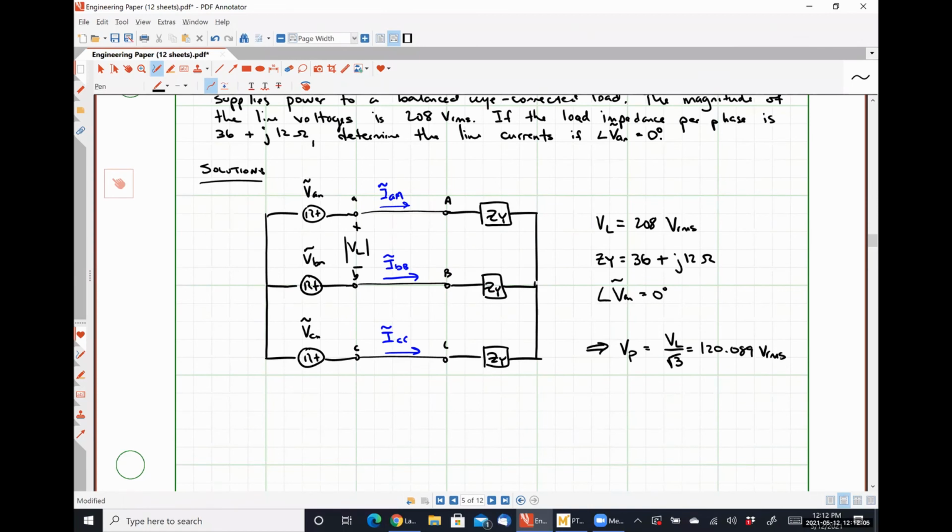So you might say, if you had a substation, the A phase might go to one neighborhood, the B phase might go to another neighborhood, and the C phase will go to a third neighborhood, so that hopefully, roughly speaking, all of those balances cancel each other out so that the system looks reasonably balanced. One street might be connected to the A phase, the other street to the B, and a third street to the C. Does that make sense? Okay.